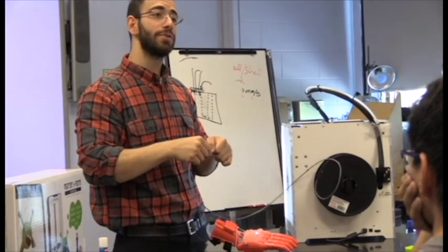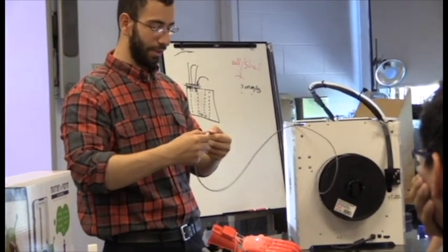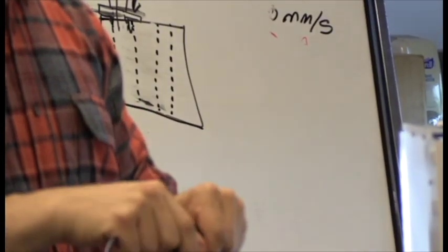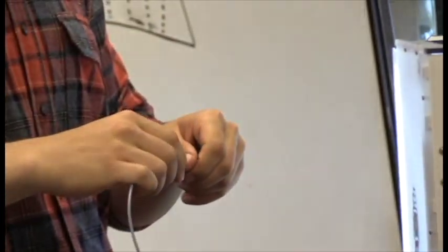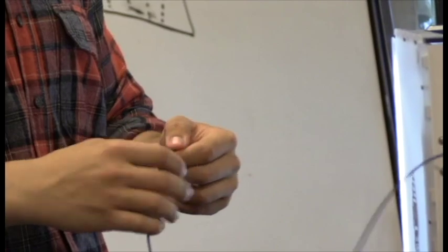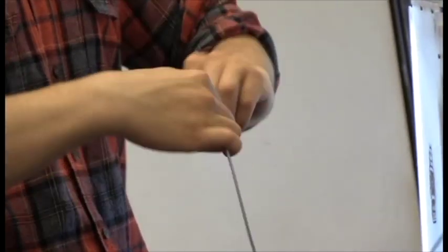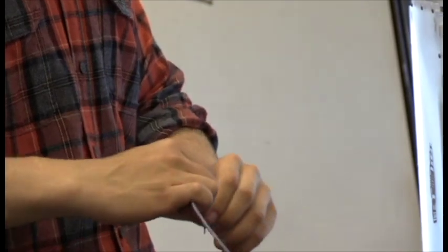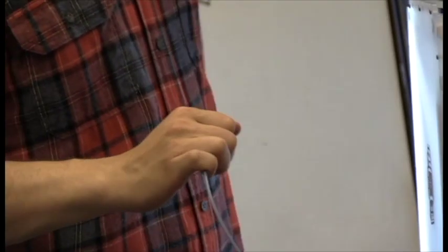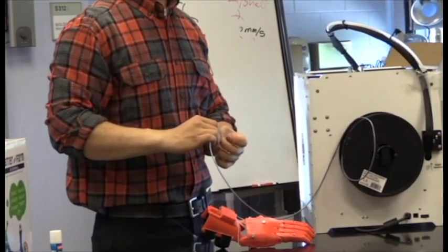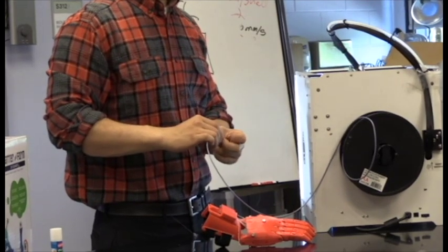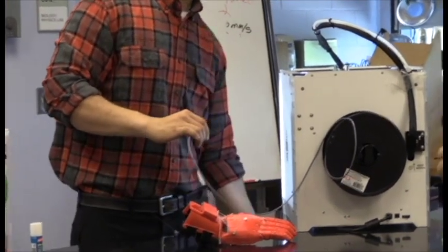The way you tell if filament is good or bad, grab it and twist it. If it snaps, if it's hard and brittle, you guys know what brittle means? Like shock is brittle, it snaps. If it's mushy and it takes a while for you to rip it, that means it's good filament. Okay? You never want to have the filament by the sun or in the window. You never want to have it outdoors. You always want it in a concealed cabinet.